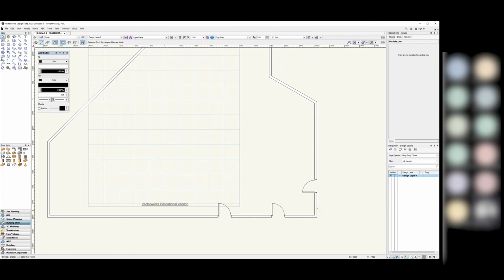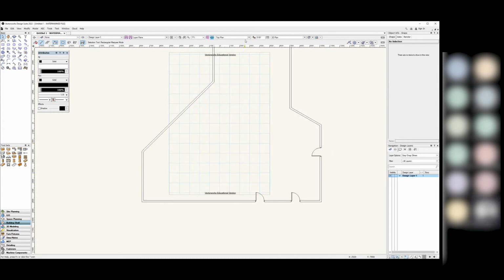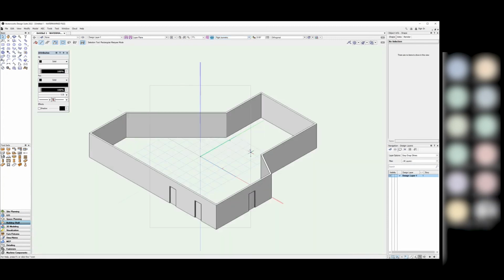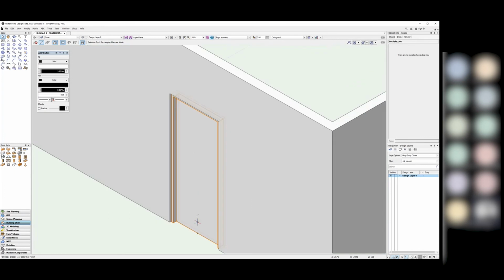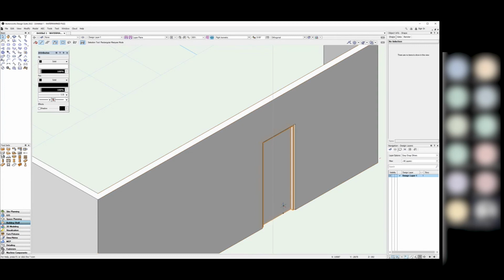And the great thing, the thing that I absolutely love with Vectorworks, is that if I decide that actually, maybe I don't want this door placed there, I can simply click and drag it anywhere along that wall. It's going to fill in where it was before, and it's now going to cut out that part of the wall elsewhere. And the even better thing is when we put this back onto our right isometric view, you see that it's now actually placed 3D doors into our building. It's already cut them out, it's already placed frames in there, and it's got the door panels and everything.